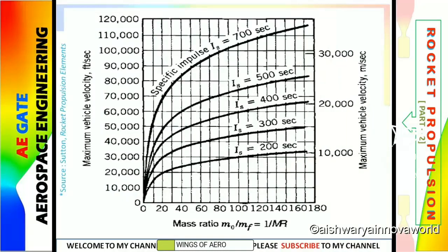So now this is a graph I have found from a Sutton book. What this graph explains is the reciprocal of the mass ratio, that is 1 by MR. What is MR? That is the final mass by the total mass. This graph goes from 0 to around 180, and in the y direction we have the maximum vehicle velocity in feet per second, and here it's the impulse.